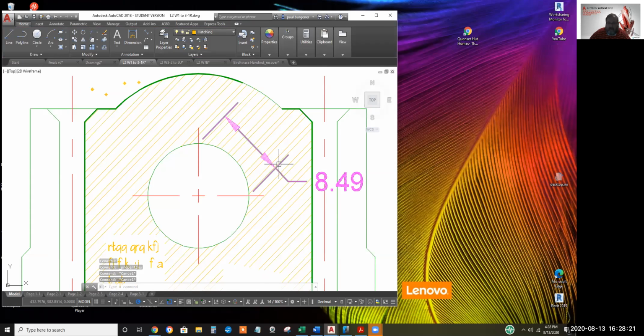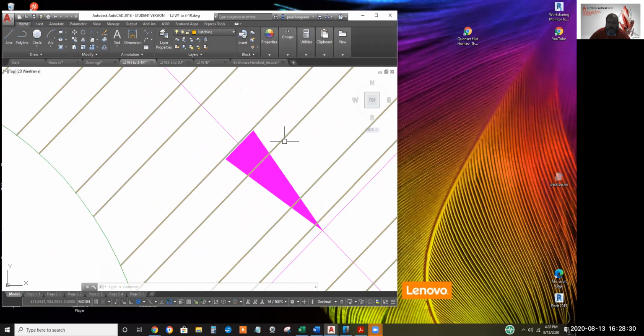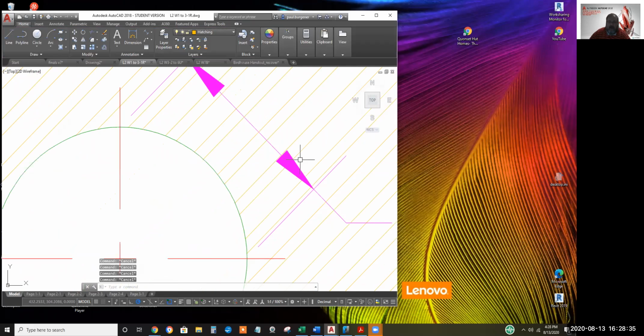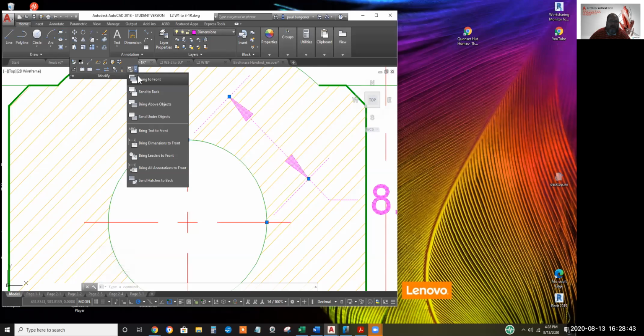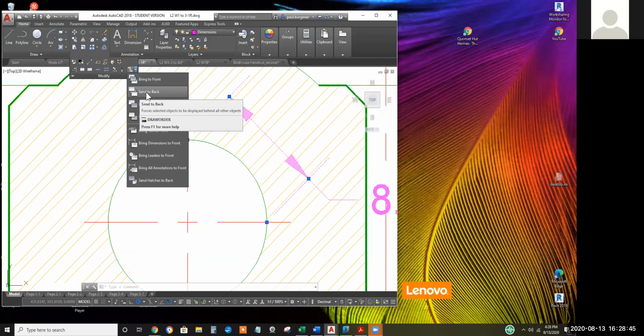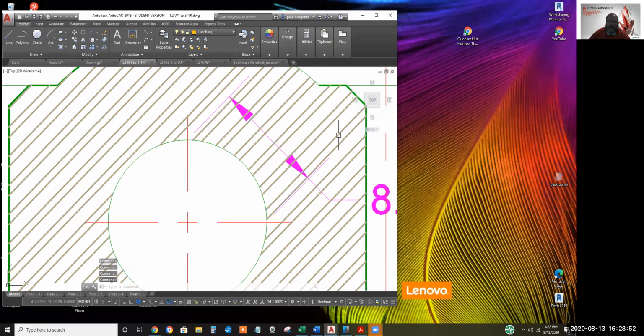It appears that the magenta of the dimension is going to print out, not the orange of the cross hatching. Looks like it's on top. Right. Now, if you want to cheat, keep it white for whatever reason, don't forget you got this draw order process. That's the one, yeah. I can send the dimensions to the back of the stack. That's it. There you go.